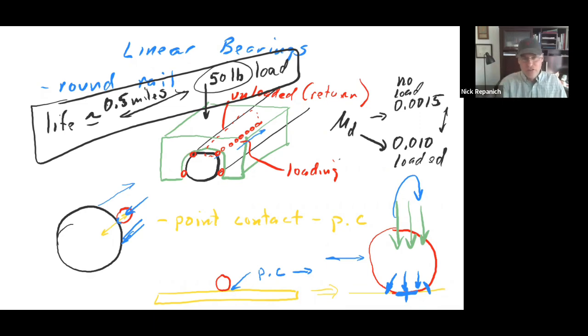And so you say, here's the load, how far will it go before you start to see grooving here, you know, before you start to see little grooves in this spot of the bearing where the bearing touches, and it starts to erode the surface finish, and it's no longer a smooth bearing, and then you just throw it out.